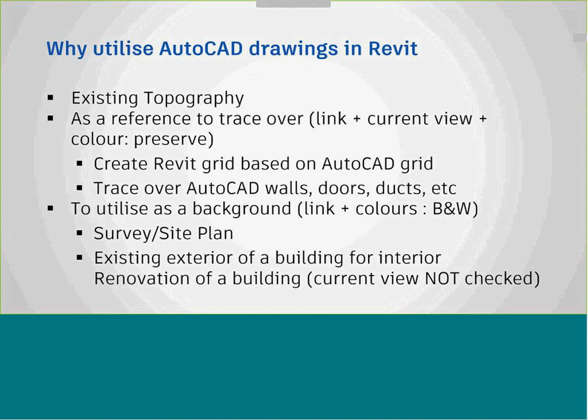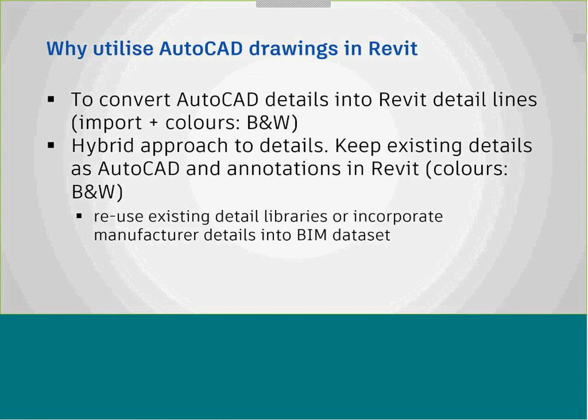Of course, bringing in CAD files to create topo surfaces, as I had mentioned some time back, or as references to trace over when you're converting a 2D layout into a 3D layout, or just to utilize as a background where you don't want to model a background. So for example, your site, if you've got a civil engineer and they plotted out the site and you just want to show that in your, for example, architectural layouts, you can do that.